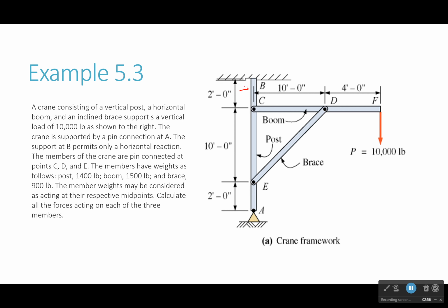We have this one beam right here, which is held in place by the little slot, and it's got a force applied 2 points along its length and pointed in. So that's 4 forces, that's a multi-force member. So right here, 1 force, 2 force, and then there's a 3rd force right here, also a multi-force member. So this turns into a frame. We can't use just method of joints, we can't use just method of sections, and so it's going to be better to look at each member individually.